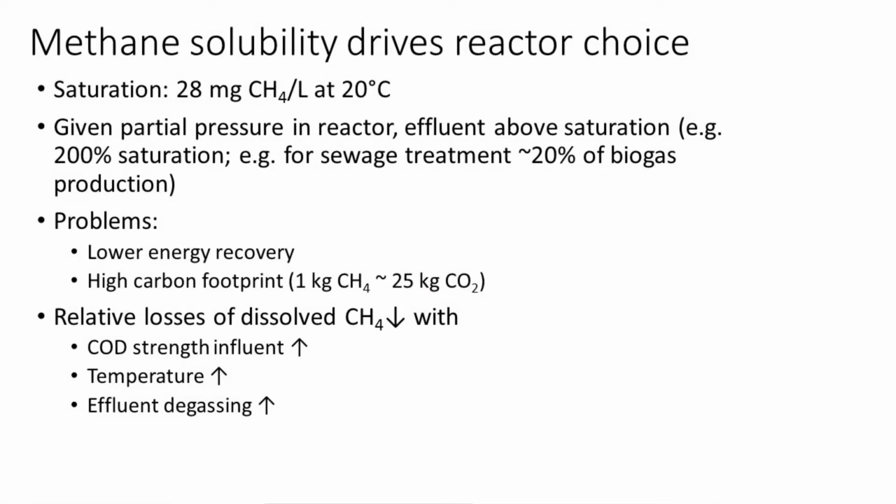Of course, if I have grams and grams per liter of organic matter, that little bit of methane then actually becomes a very little bit in comparison. So the stronger the wastewater coming in, the less of an issue it is. Gases also have lower solubility at high temperature, so if I work thermophilic, less methane is staying behind, and that's also better. I can also technically intervene, and on the effluent coming from the digester, I can put a degassing unit and really pull out the methane, so I have low emissions.